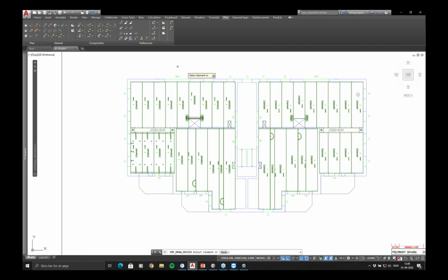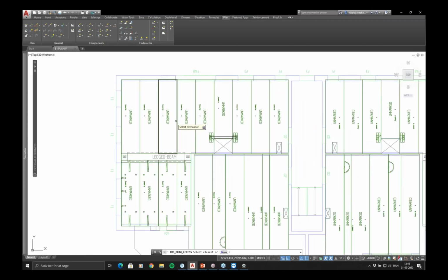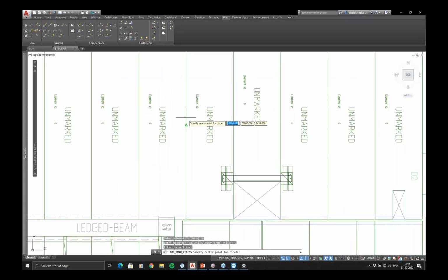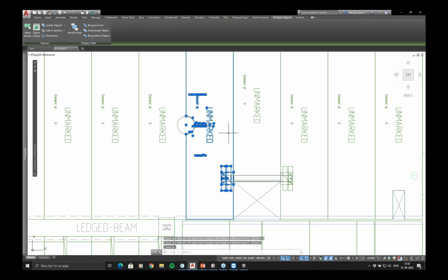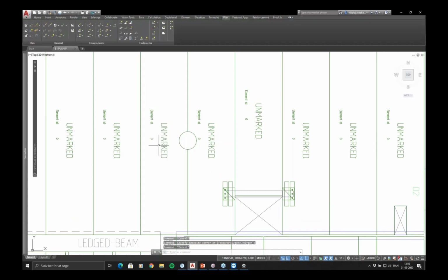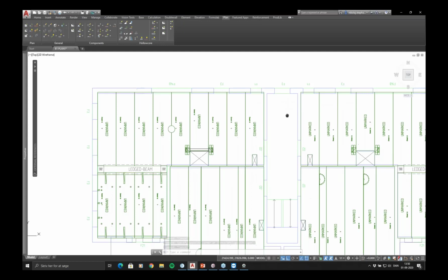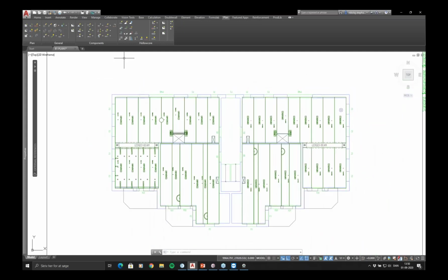And now, when I mentioned a round recess, let's just add one in for the fun of it. I don't want to choose an element, but I want to make a circle. I want to make that circle here. Actually, I want to make it between two elements. So what happens if I do that? We pick these two guys here, we add the hole to them, and basically it adds half the hole to each of them, of course. So it split that one polyline that I drew over these elements here.